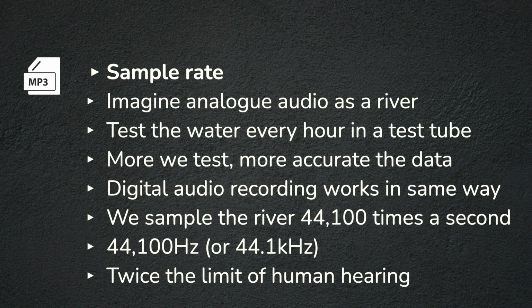If you think about vibration, all sound is a vibration, and so it's like a wobble, right? So if you think of a jelly wobbling, it wobbles from left to right. In waveforms, we think about it visually as wobbling from top to bottom. And in order to accurately represent audio, we need to take the top of the curve, the top of the wobble, and the bottom of the curve, the bottom of the wobble. And so we need to be able to do that 44,000 times.